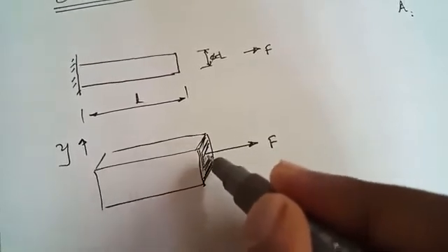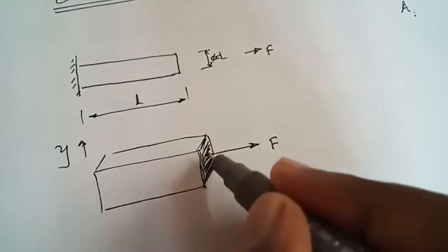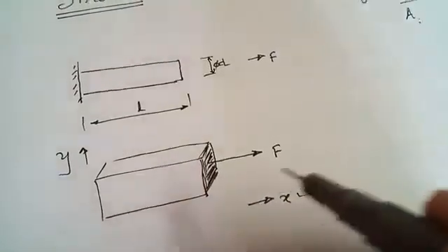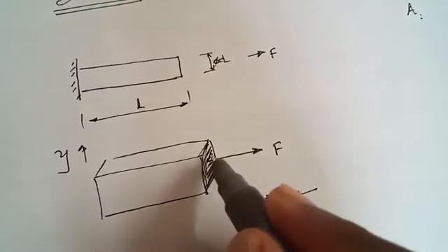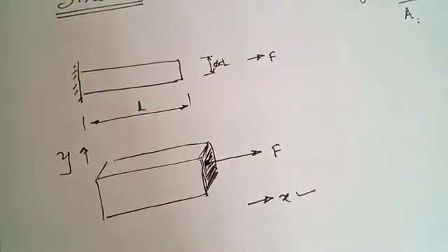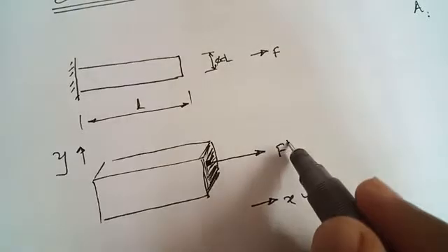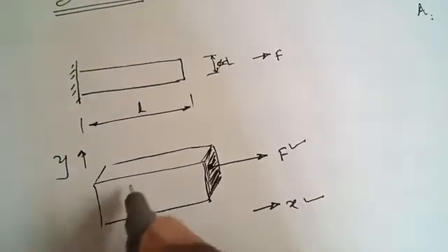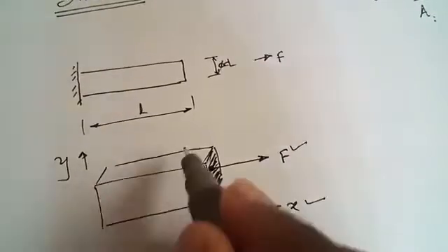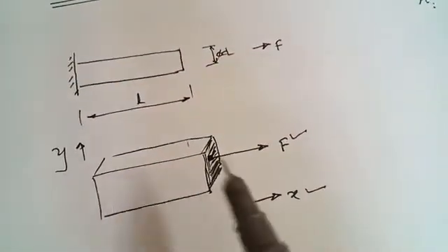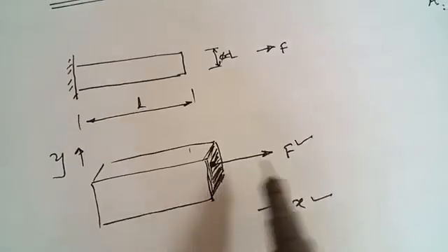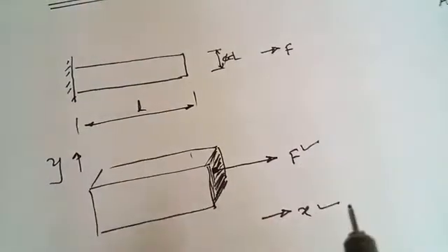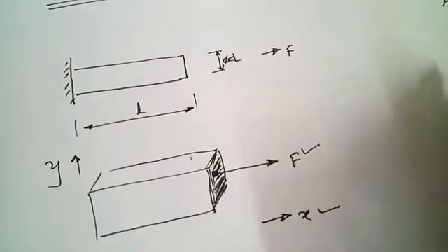When we are going to find out the stress, we have to take the area which is normal to the direction of the force. So you cannot consider this as an area or this as an area. No, it is the area which is normal to this force. So this will be the area.